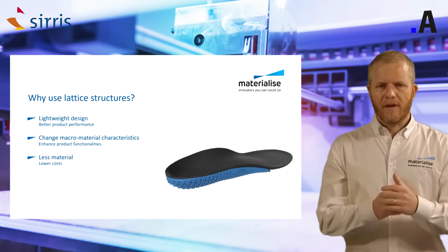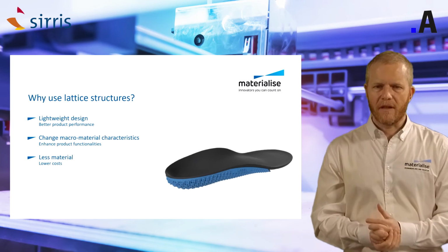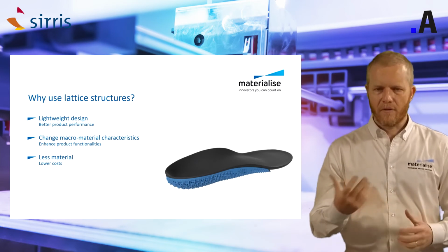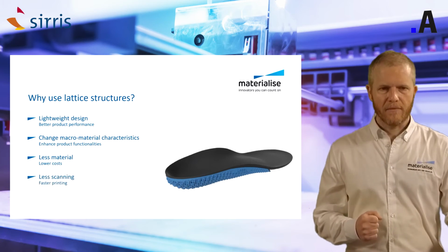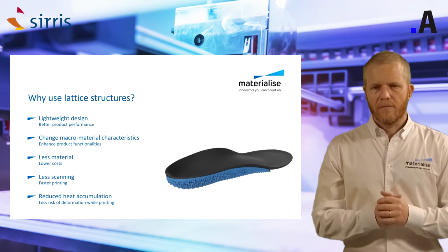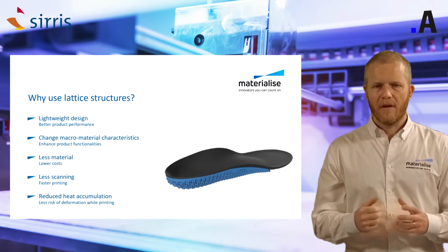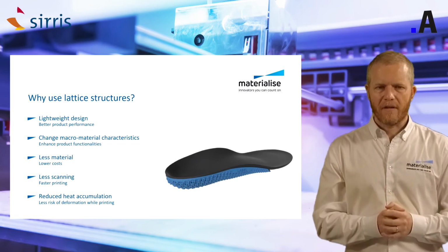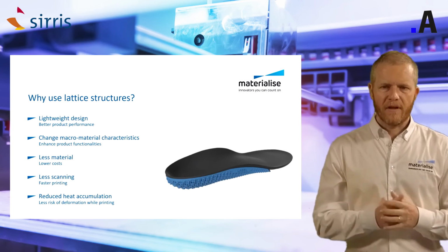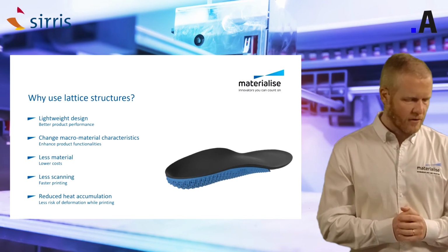So also by using a lattice structure, it will use less material and thus lower cost, and also make it print faster. And also, so this is more for laser machine printing. By having less material and less cross-section, we will have less heat accumulation and so less risk of deformation while printing.